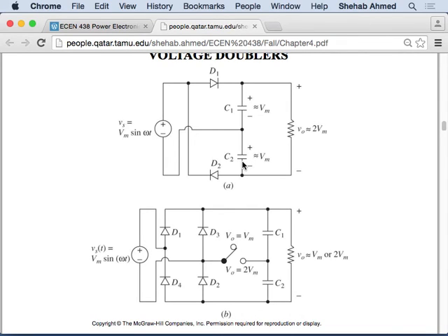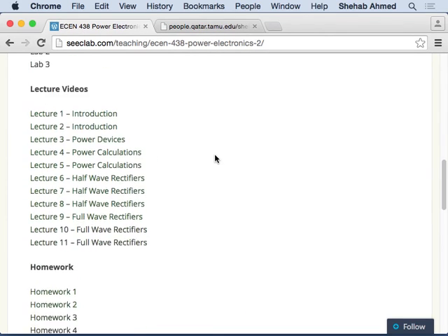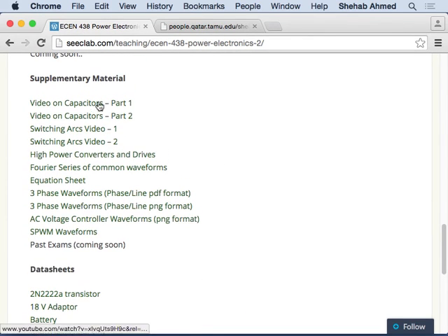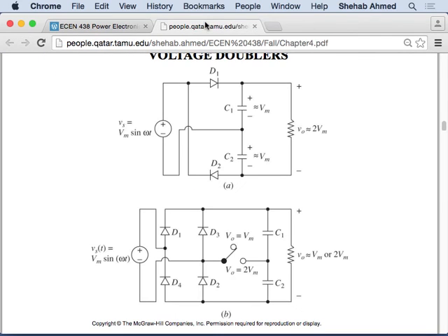Some capacitors are bipolar devices, and some are not. Electrolytic capacitors are not. If you put a negative voltage across them, they will blow up. It's the construction of the capacitor. I put some videos about the different capacitor technologies. It's good that they brought that up. There are some videos here by a really funny guy. He discusses the different types of capacitors in nice 10-minute videos, just for knowledge, so it will not affect your circuit understanding here.